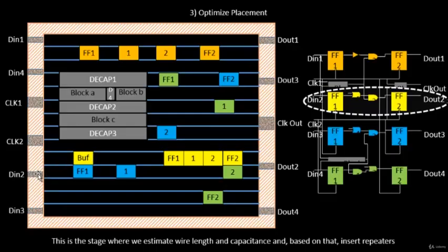You send the signal from D in 2, it gets received by the buffer. The buffer again reproduces it and sends it to the next buffer. This next buffer again reproduces it and sends it to the flip-flop. So in this way, the long distance has been cut down to shorter distances, and whatever D in 2 is sending, flip-flop 1 will be receiving in a proper integral manner without any deterioration, with the help of these repeaters or buffers. So that's the job of the buffers.